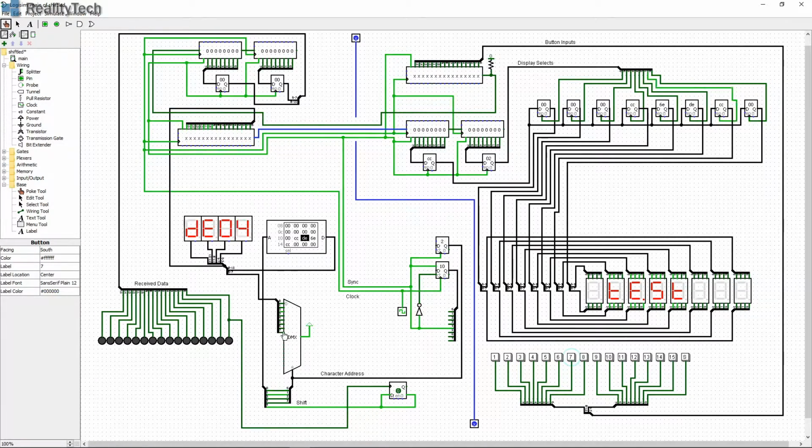So we've got a multiplexer here which generates the 8 selects that we actually need to select the displays. And as you see, as that counts up, our selects are going. Our selects are busy here. I will go into this when we get over here because this isn't the way you do it in real life. You might do, but it isn't the easiest way. So that generates our selects, and then we'll come back to the shift as well. So our selects go out to the shift register.